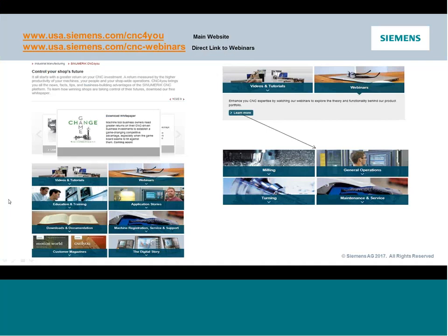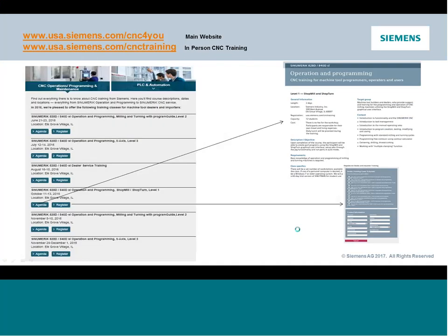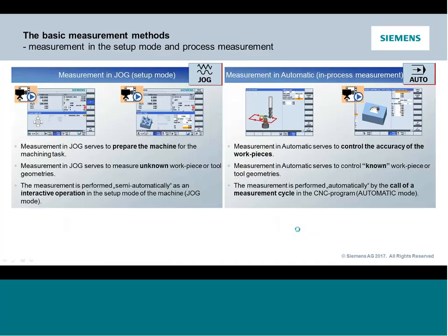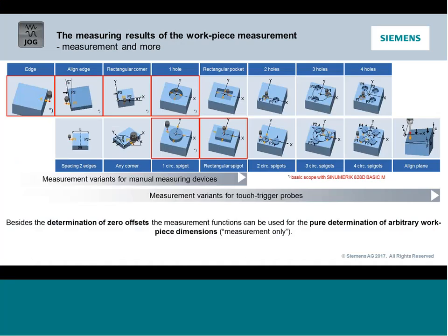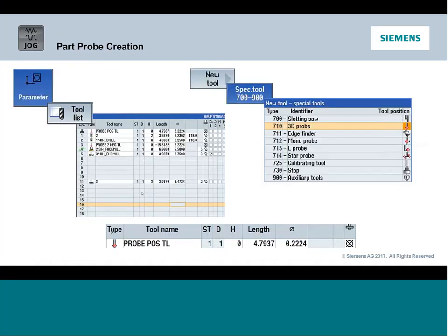What types of probes are supported? So if you recall back here, in the beginning, I showed you quickly building a probe. So these are the probes that we support. So a straight 3D probe, the Type 710, that's a probe that can measure in all 3 axes, typical Renishaw, Marposs, Blum. We have monoprobes. Those are probes that can only take measurements in a couple directions. We see these a lot more in lathes and stuff like that.